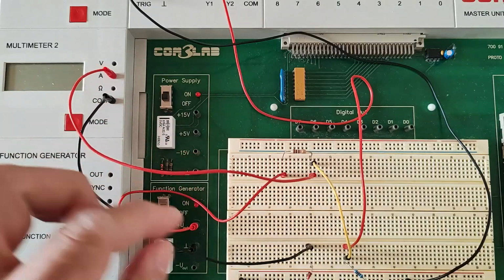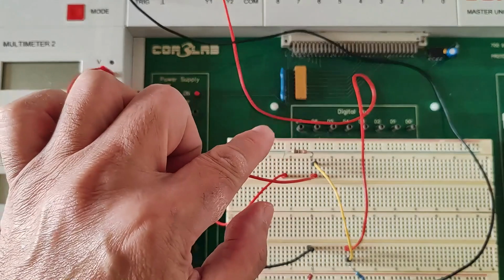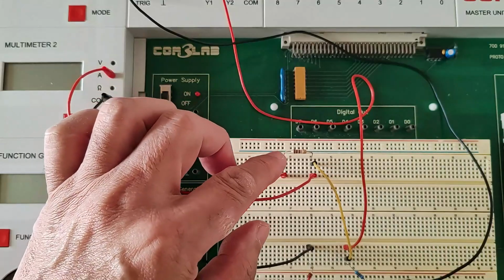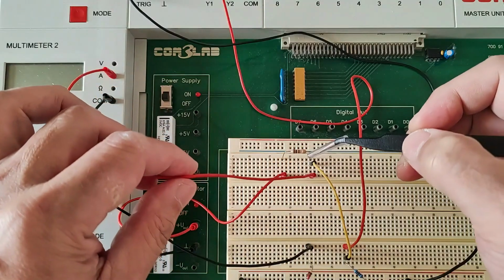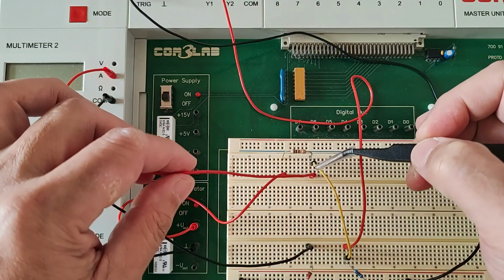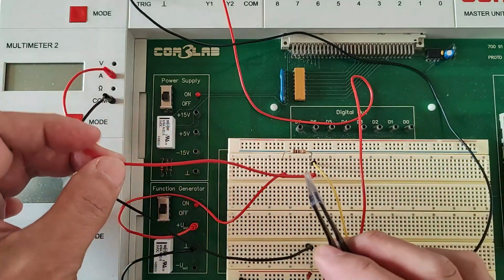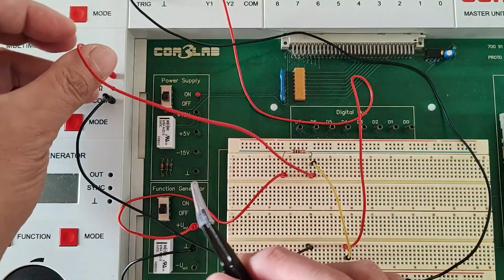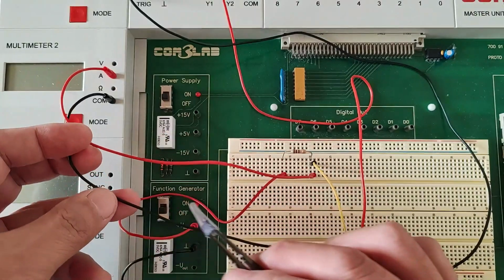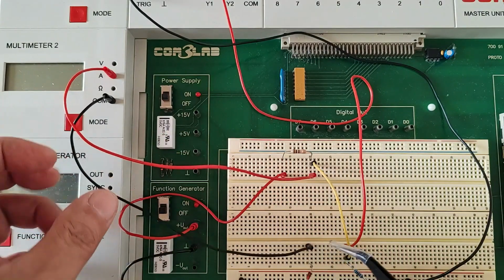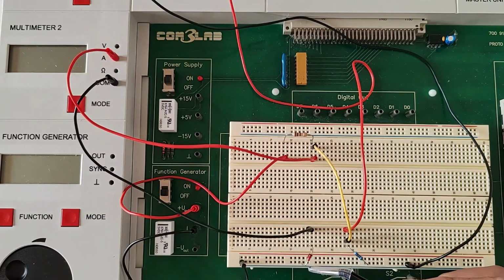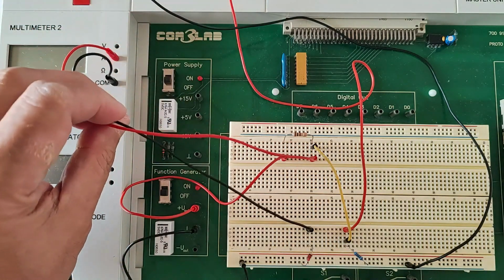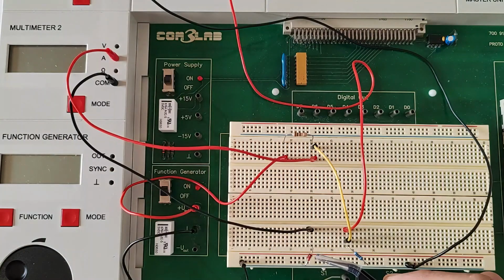Now, what will happen here, the current that will be coming from the source will first pass through our limiting resistor here, and once the current exits the other leg, that current will pass through this wire, going through multimeter number 2, and come out of the black wire, and then eventually pass through our Zener diode. That's what I meant earlier by putting multimeter 2 in series with our Zener diode.